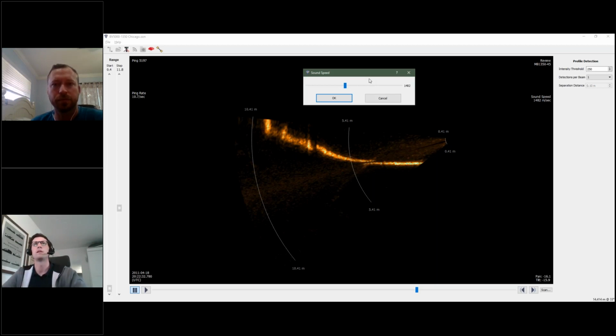It's not, I would say, as important as with a traditional surface vessel mounted multi-beam, but it all depends on what you're doing. Like I have said dozens of times, it's very application dependent. If you do require highly accurate measurements, we do recommend getting at least a temperature of the water, or really having a sound velocity probe on board that you can stick in to get an accurate sound velocity.